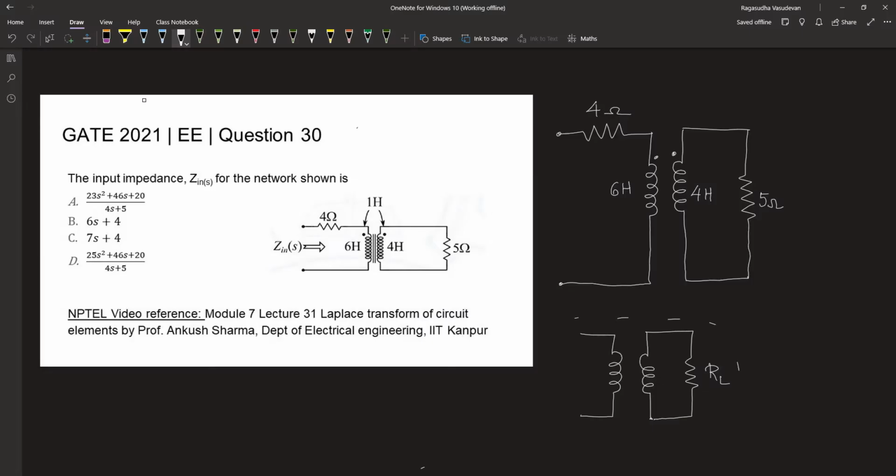Consider this coupled circuit. You have the current that is entering into this terminal, and because of the magnetic induction, this magnetic field and the current that is passing through it induces a voltage across the secondary coil. So in the secondary coil, the current flows in this direction. So the positive of this is here and the negative terminal is here. So the voltage is measured across these two terminals and this voltage will be the voltage across the secondary.